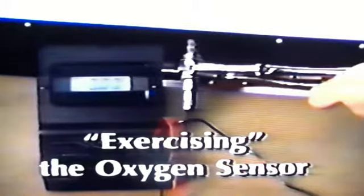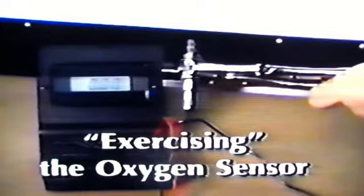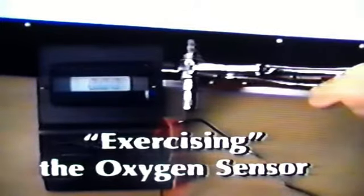The meter reading should drop to less than 0.2 of a volt in 4 seconds or less. If you see this kind of drop, you know the sensor is probably working all right. But to be sure, you should repeat the test 3 more times. This is sometimes called exercising the oxygen sensor. And the faster it responds, between 0.8 and 0.2, the better, because this assures a proper air-fuel mix.